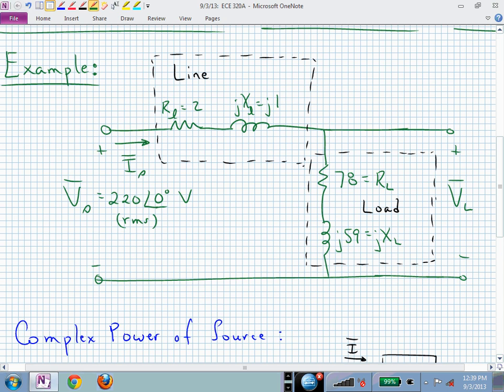So now I want to know, there's two different ways of looking at this. You could say my source is supplying power or it's absorbing power. And those should be just the opposite in signs, correct? Typically you would think, okay, the source has to supply power if it's the source. But if it's supplying power, then the current needs to be coming out of the positive terminal and not going into the positive terminal.